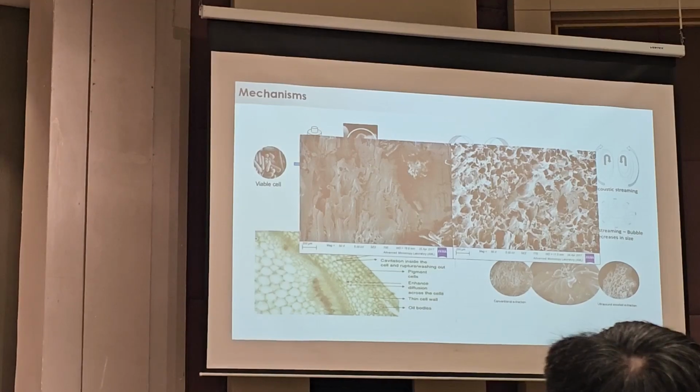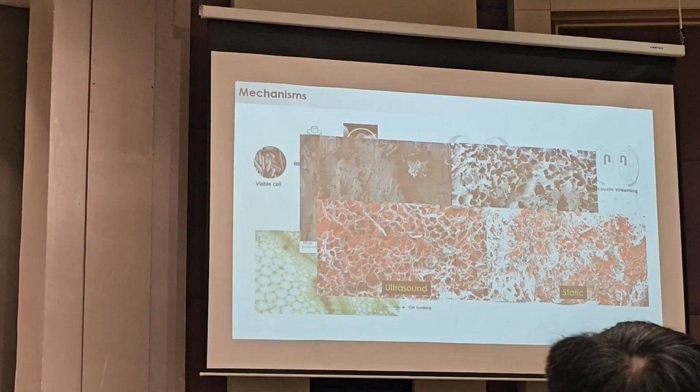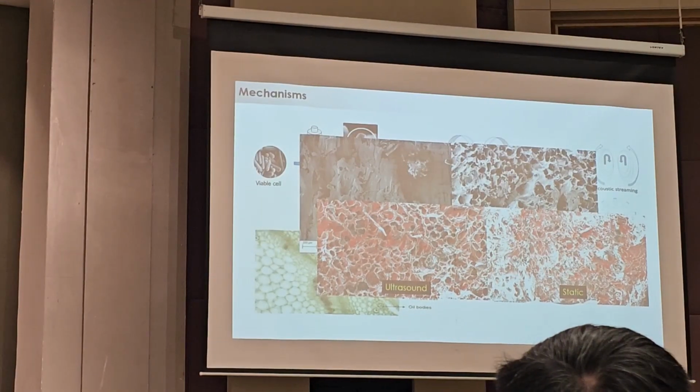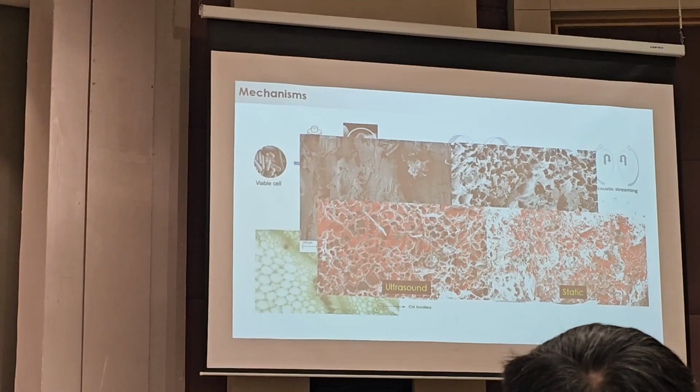Because of these cavities, what happens is it allows the solvent to go in, and you will see over here, the red dots are sodium, which you add to the substance. The static one was mainly on the surface, whereas in this case it allows the sodium to move in. This was done with EDX to see how these things are migrating into it. So this shows the cavity formation. That's the single most important principle which helps in ultrasound.